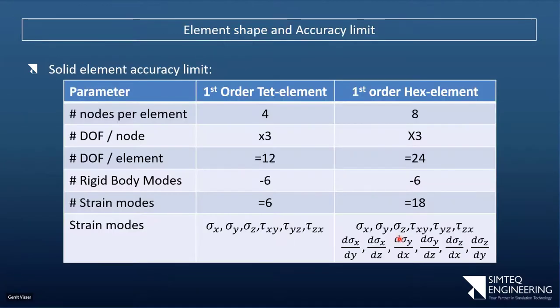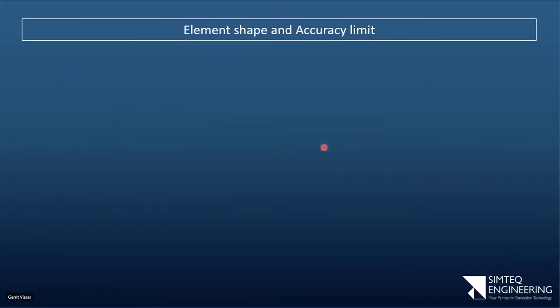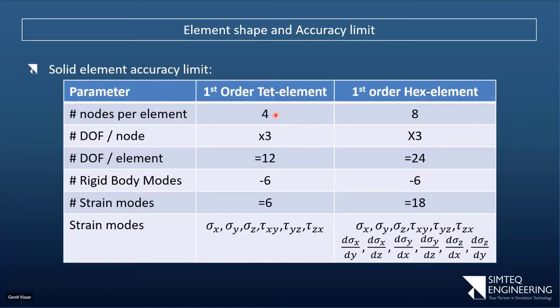And the same way, if we look at solid elements, let's compare the 2 extremes. So again, the element that's defined by only triangular faces and only quadrilateral faces. So if I look at the number of nodes, I've got 4 and 8. So there's now a lot more nodes there, as opposed to, if I look at the previous slide again, where it was 3 and 4. If I multiply that node by the number of degrees of freedom for the node, in this case the translation X, Y, and Z, I get 12 degrees of freedom for the element and 24 for this element.